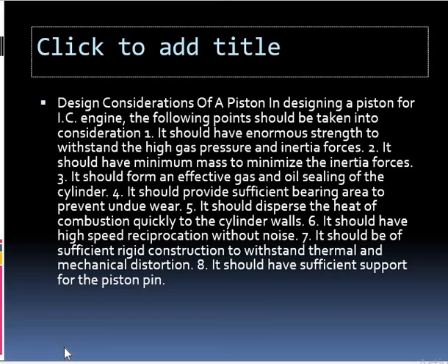So what is the design criteria? First, it should have enormous strength, and it should withstand gas pressure and inertia forces, and provide effective gas sealing of the cylinder. That is the main design consideration.